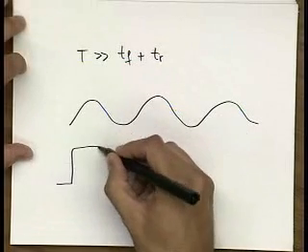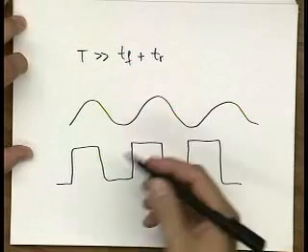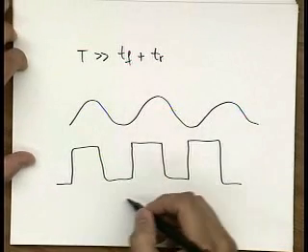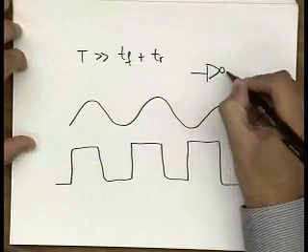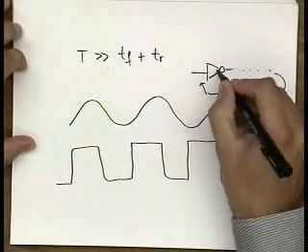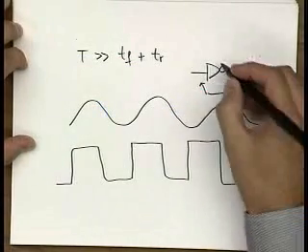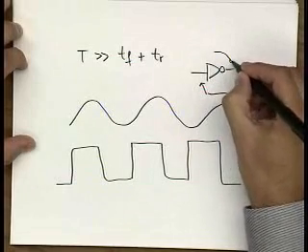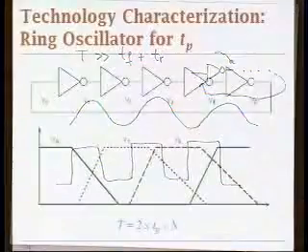Ideally, you would like to have a really good quadratic waveform for which you have to have a large number of stages, so that you make sure that if you go around the oscillator, next time you come back to this point, all the transitions related to this gate have been settled. It's not that this gate was somewhere in the middle of a transition and you trip it with another switching event. Okay, so go back to slides, please.